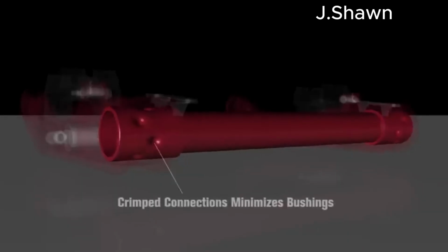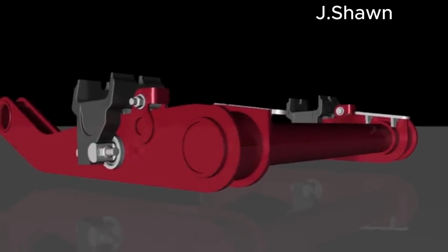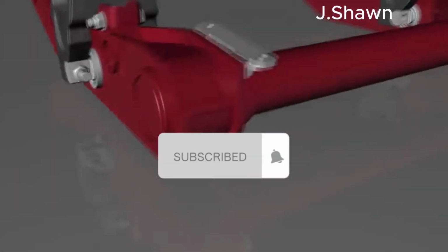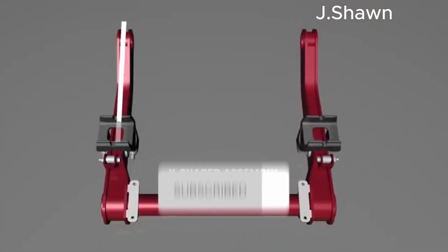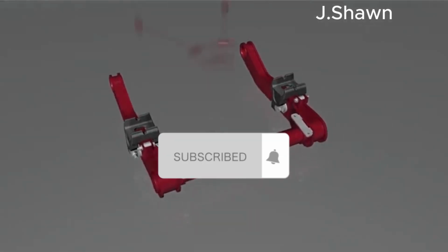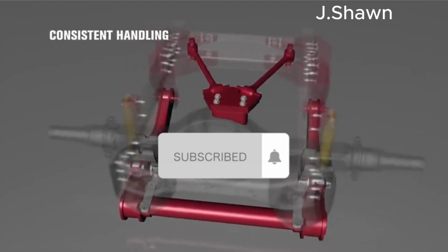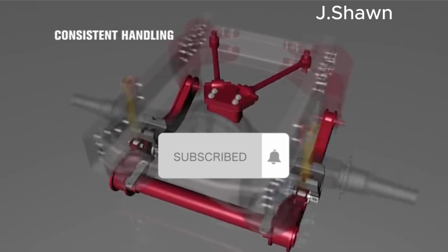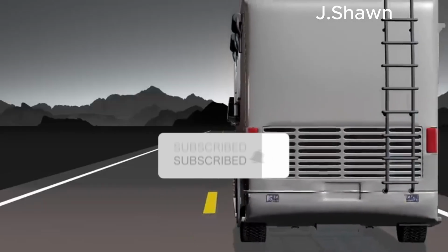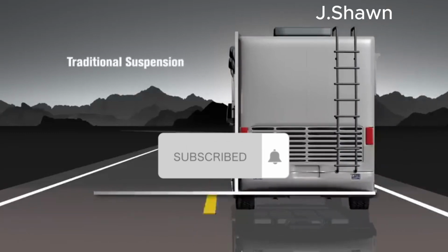The transverse beam of the V-Ride suspension is directly integrated with the trailing arm to form a single-piece U-shaped assembly. This unified design eliminates bushings connections found in traditional rear suspensions, providing superior rigidity. The integrated U construction and V-Rod control arms combine for less sway and a more stable ride. This is particularly noticeable to motorhome owners during curves in the road or when traveling over uneven campground roads.